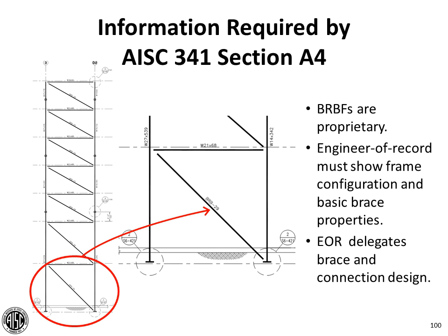Then the last basic thing that I'd like to talk about is another proprietary system. The beam column connections for special moment frames. There are some proprietary connections. Here, the basic element that makes a buckling restrained braced frame, that's the BRBF, those are proprietary. And so again, the engineer of record has to convey enough information so that the design can be understood by the fabricator or the contractor bidding on the project, as well as by the building department to make sure that the design satisfies the requirements of the building code.